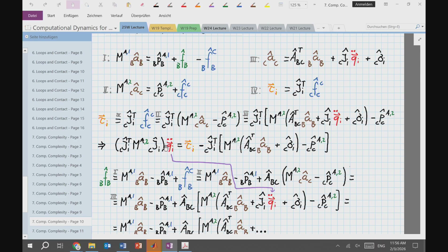So I have this projection. Again, I did some projection where I moved from one coordinate system, generalized coordinates, into a new coordinate system, just at one joint, right, with its 1 to 6 motion primitives. And we see the same form here, right? Some Jacobian times mass matrix times Jacobi transpose. This is how we computed the mass matrix for the original system, right, where we went from some other space, Cartesian space, into our generalized coordinate space. Now we go from the generalized coordinate space to our joint space. And we do exactly the same thing, right? We project it again. Same idea.